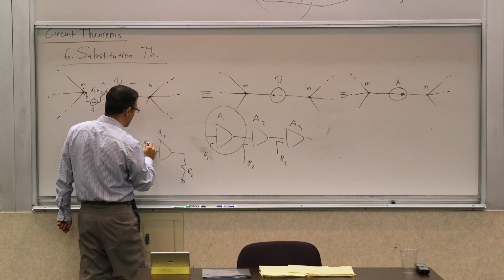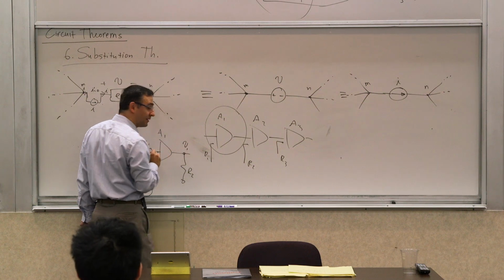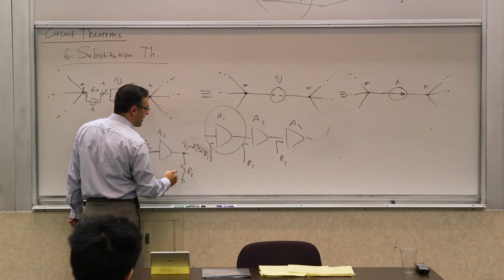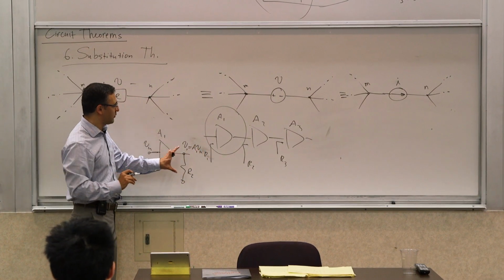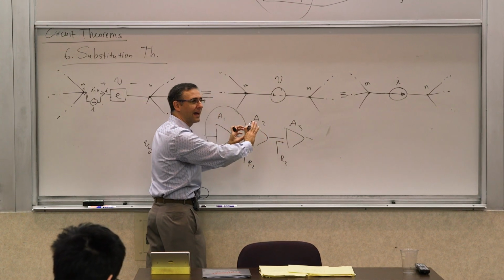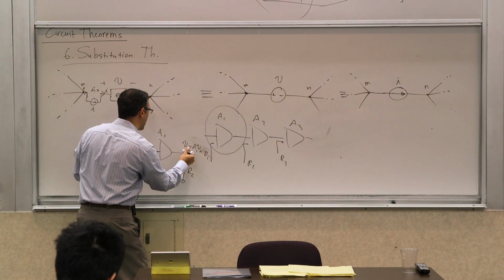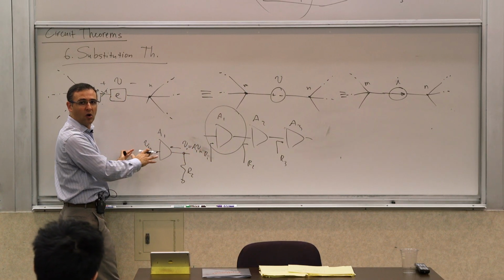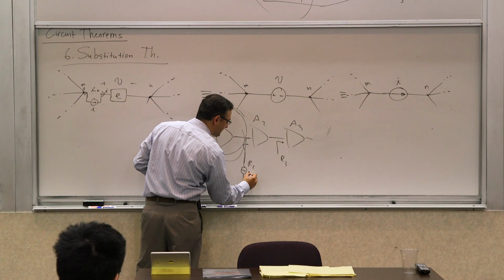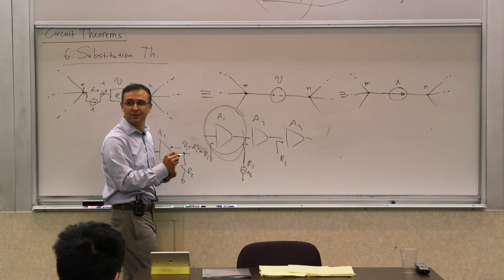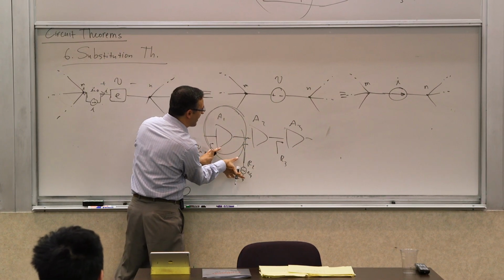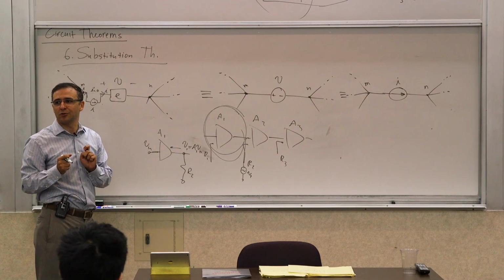And I calculate a voltage. So this is V in. This becomes some voltage, some V1, in terms of V in, with some proportion. It becomes A1, V1, V in, right? That's the voltage that this network will have at this point. When you want to analyze the second amplifier, you don't need to worry about what's inside this thing anymore. All you say is that I substitute all of this with a voltage source of V1 now, because I know what this voltage is, it's V1, and I assume that it's driven by an ideal voltage source at that node.